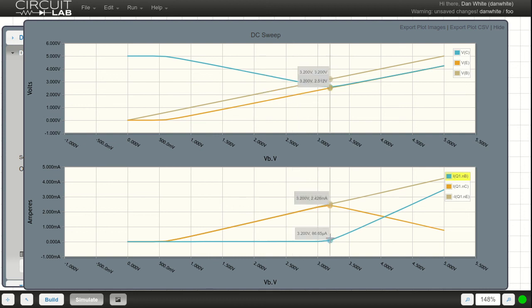As soon as we hit saturation mode, or actually effectively in saturation mode, the base current rises up, collector current decreases, stays positive. You notice the emitter current just keeps trucking right along, going up, which makes sense with your hand calculations that you've just done. I also want to point out that KCL is always true. The base current plus the collector current equals the emitter current.